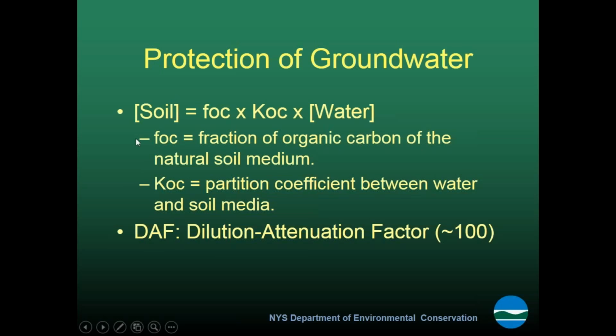One other interesting thing about the standards for protection of groundwater: most states have a soil cleanup standard set for protection of groundwater, and they tend to be significantly higher than a straight calculation of fraction of organic content times the partitioning coefficient, because you do get some dilution or attenuation of these chemicals.